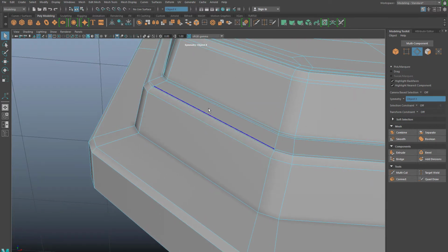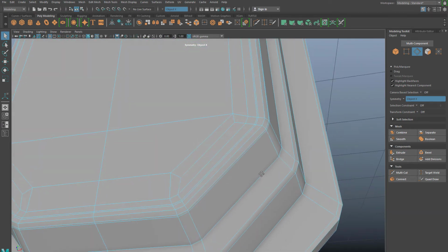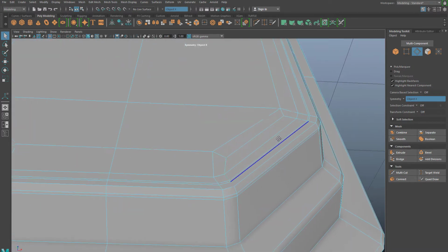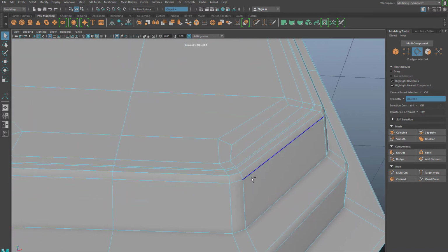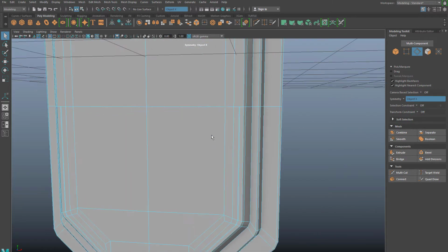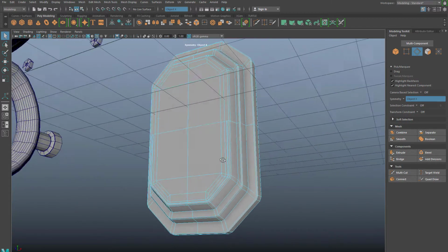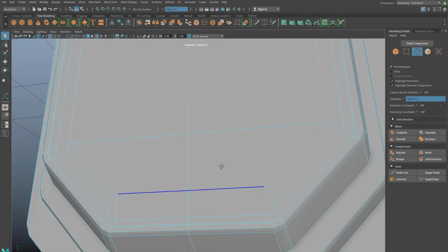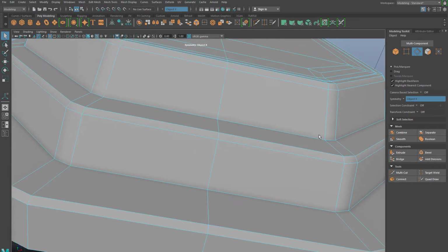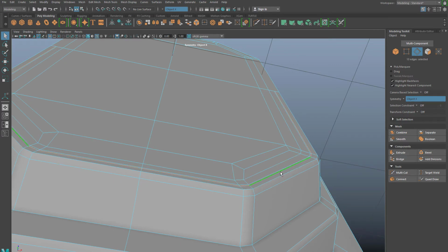I believe that was a mistake from the poly reduce. You have to be careful when you do these auto-magic sort of things. It can remove things that you don't necessarily want removed, or change things in a way that you would have manually caught. It's one of the things that when I double click to select an edge loop, I delete. I want to check again on everything to make sure that did not affect something I did not want it to affect. But most of these seem to be terminating at that halfway point, so it should be just fine.